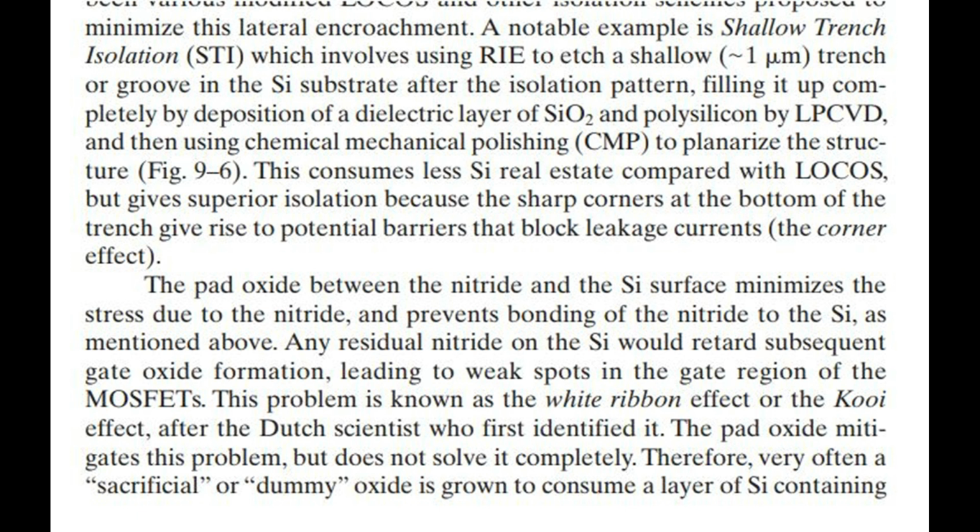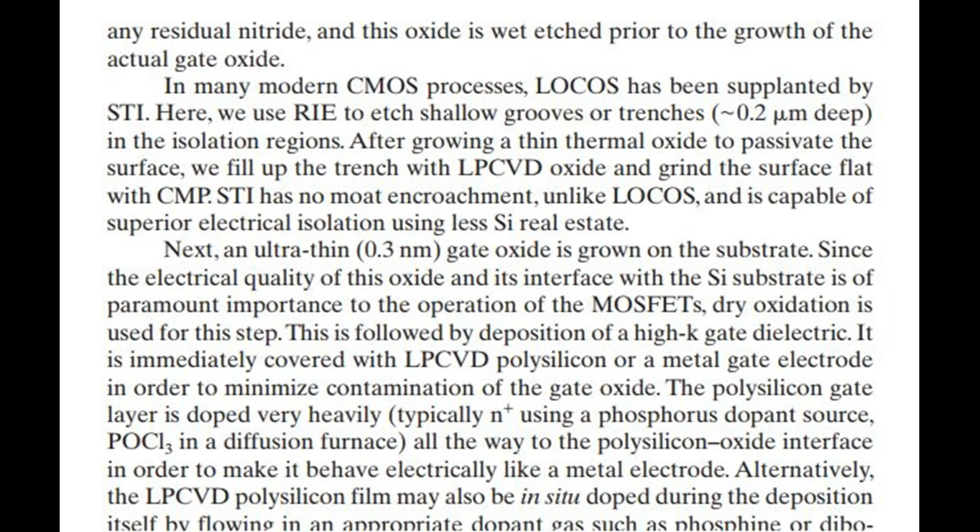This problem is known as the white ribbon effect or the Kooi effect, after the Dutch scientist who first identified it. The pad oxide mitigates this problem, but does not solve it completely. Therefore, very often a sacrificial or dummy oxide is grown to consume a layer of silicon containing any residual nitride, and this oxide is wet etched prior to the growth of the actual gate oxide.